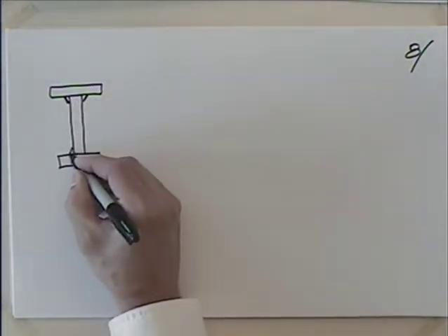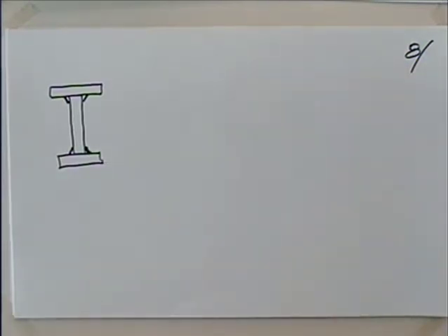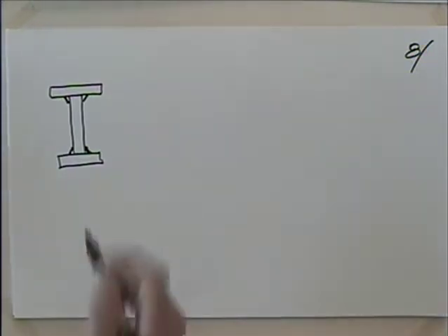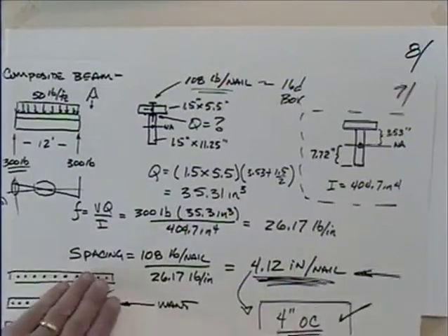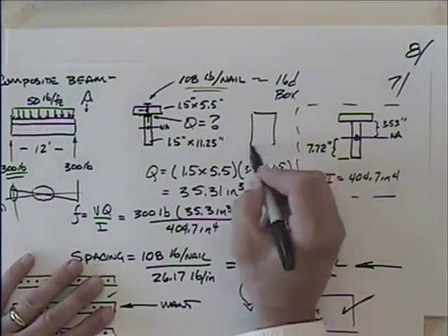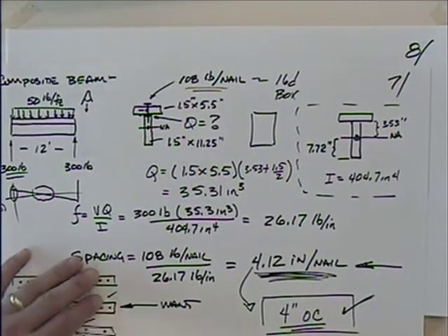Okay? You want to put the smallest weld possible. Because as you have to put a larger weld in there, you got to buy more weld material. You have to pay the labor to put that in there. And the biggest thing probably you want to try and avoid is the heat distortion. Okay, heat can be a real killer on this thing as you try and weld this up. So the smallest amount of weld that you put in there, that's going to pay off for you. You might wonder, well, where does this ever come up? I mean, isn't it more cost effective just to put a rectangular beam in this thing and be done with it? And a lot of times it is.